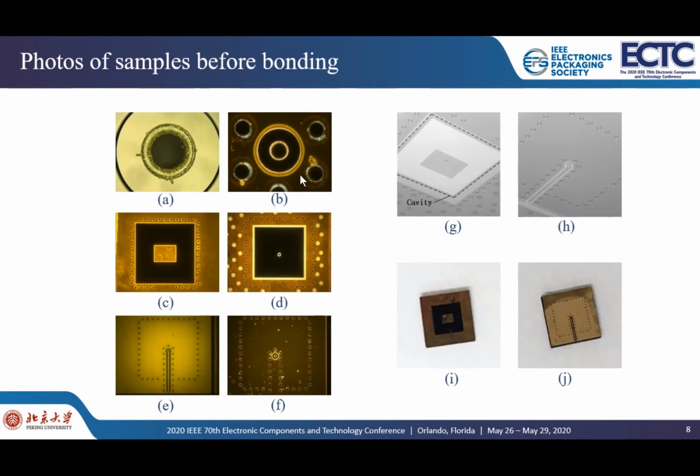Figure A and B show the photo of fabricated bonding region for vertically aligned wires. One is located at the bottom surface of top silicon interposer. The other is located on the top surface of bottom silicon interposer. Figure G and H are X-ray photos of the patch antenna after removal of seed layer. Before bonding, it can be found a cavity underlying the patch with a wire fed in near the center.